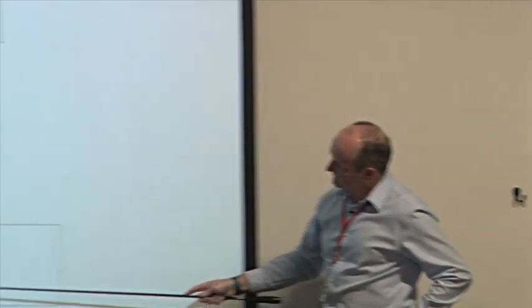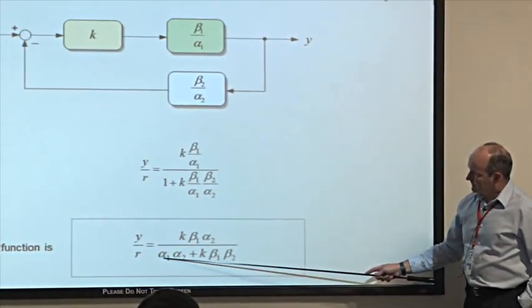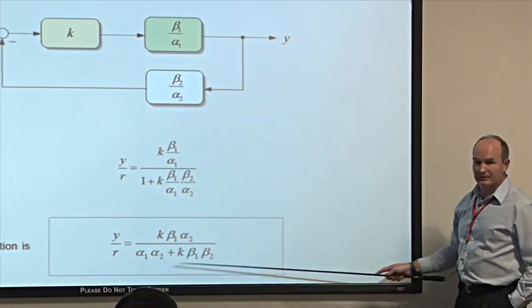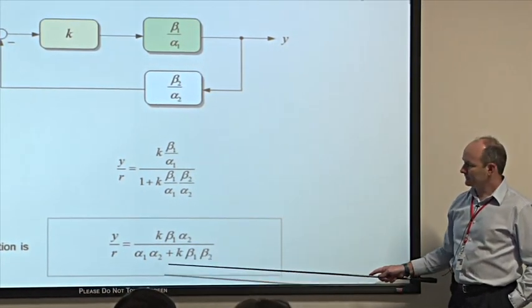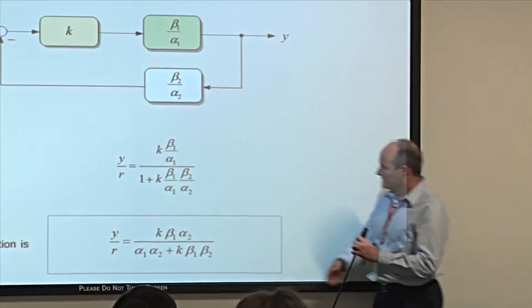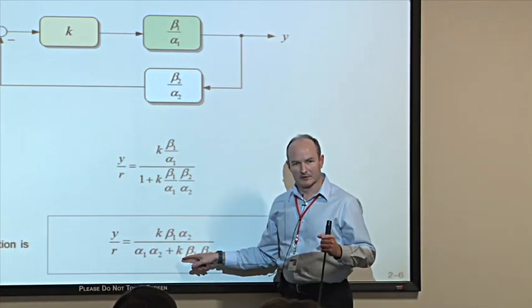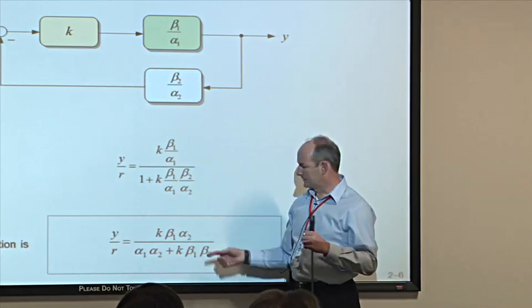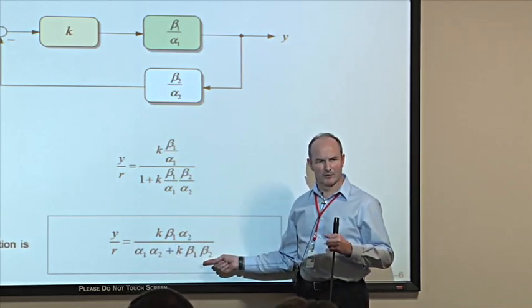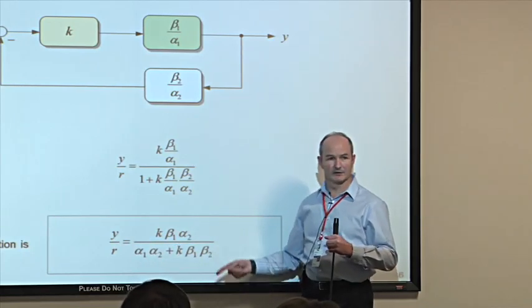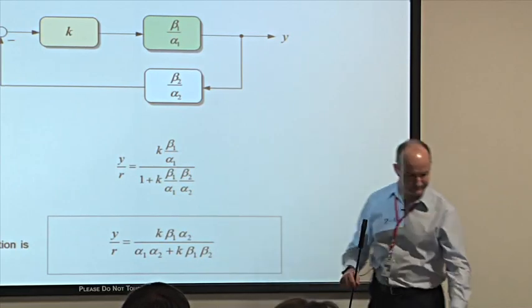So where are the poles? Not so easy to find, because they're the sum of two different polynomials, and to find each of these polynomials, we've got to expand these polynomial products, and then we have to combine like terms and refactorize them. So the closed loop poles are not easy to find. They're not obvious anyway, but they're important.